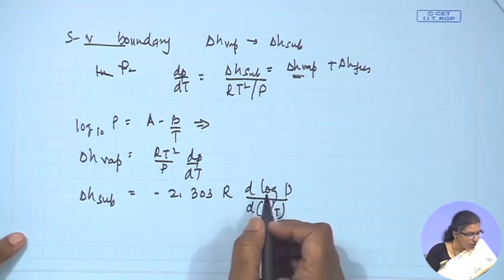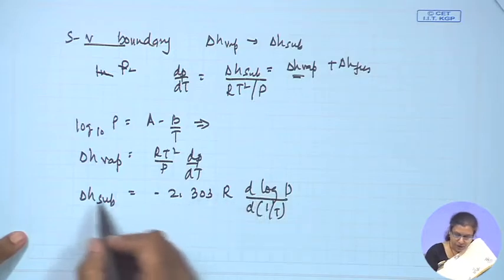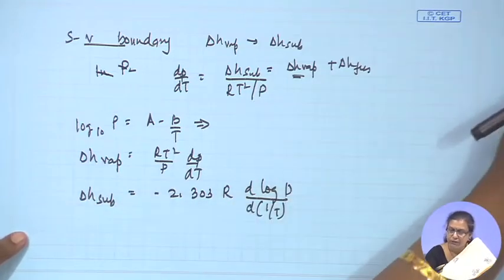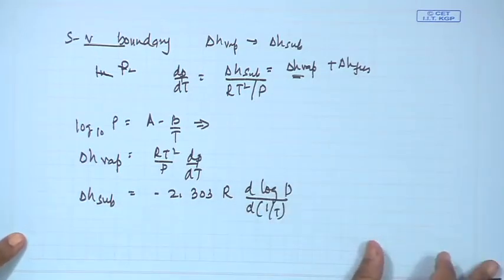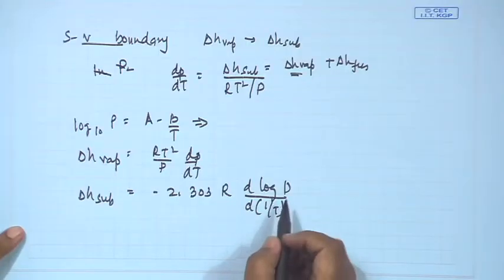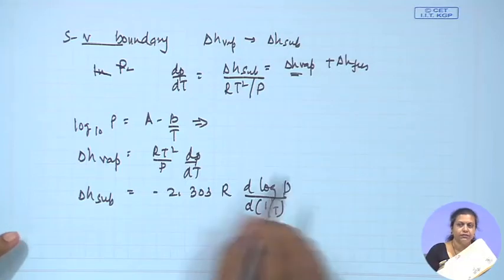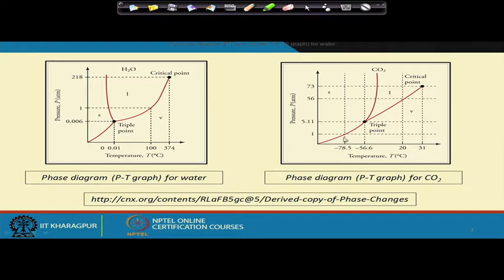So, therefore, we find that from these equations which we have derived from the basic equation of homogeneous open systems, the simplest type comprising of single component and two phases, what do we find? We find that we are in a position to predict the slope of the PT curve here, and also if we know the slope, we can predict the heats or the enthalpies involved in the transition criteria.